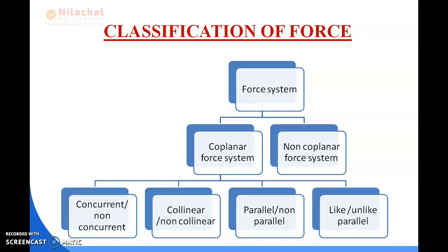They may be parallel to each other, but the direction may be different. Then the last one is the non-coplanar concurrent force, where the lines of action do not lie in the same plane, they act in different planes, but they pass through one point or are generated from one point.